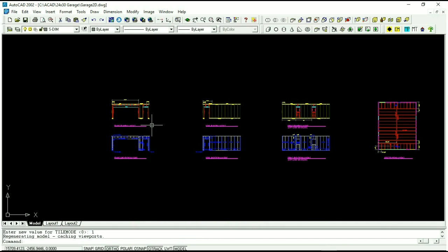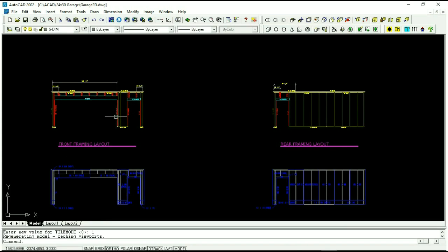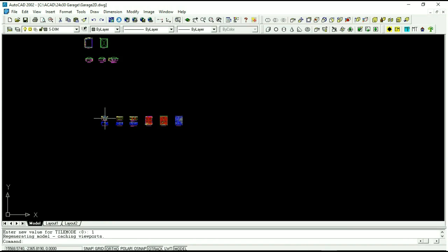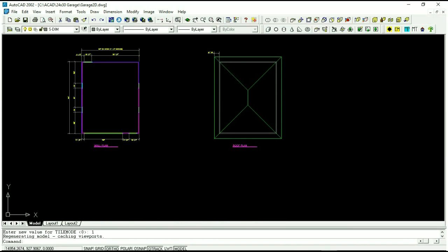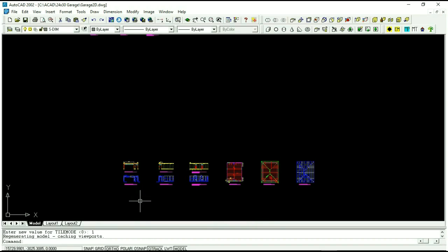So instead of trying to do the entire model in one session, break it into components. Before Inventor, that's kind of how it worked. You build parts, and then you make subassemblies and weldments, and then you take those subassemblies and weldments and put them together to make the larger product. In AutoCAD, when I was talking to people about 3D, I would always tell them, just break it into components, because if you try to build this building in one model, you get the front wall put in, but then all of a sudden you have this third axis you're always dealing with, and it ends up causing you issues